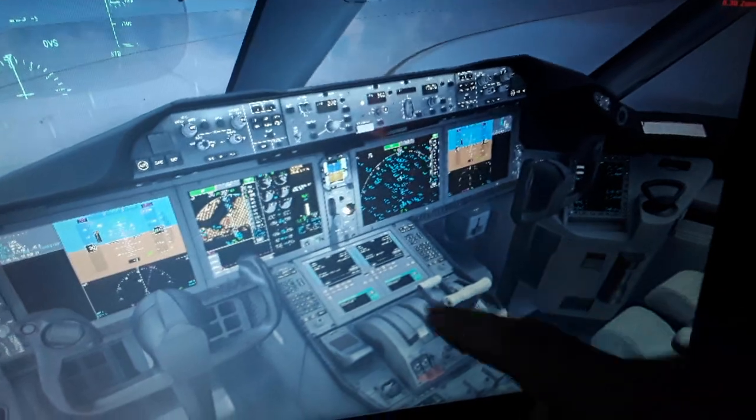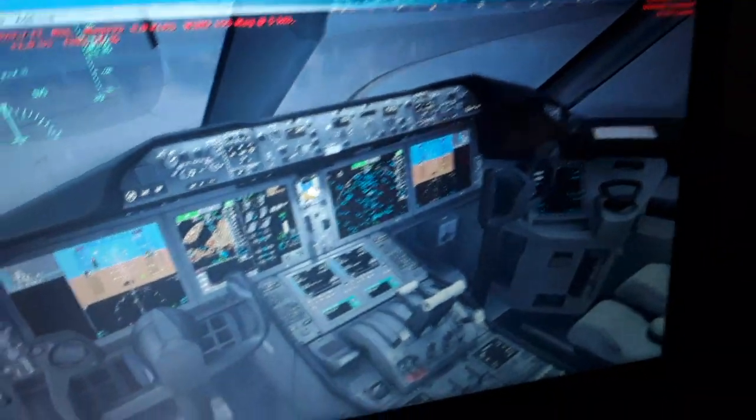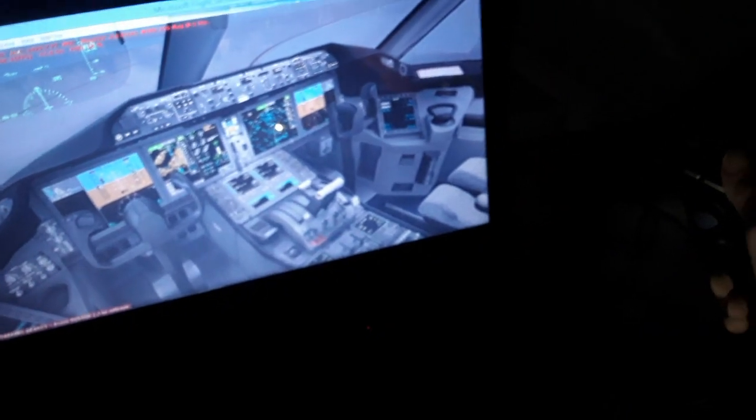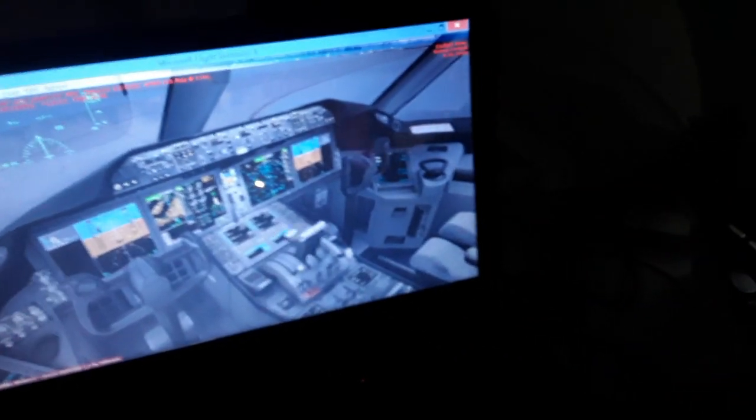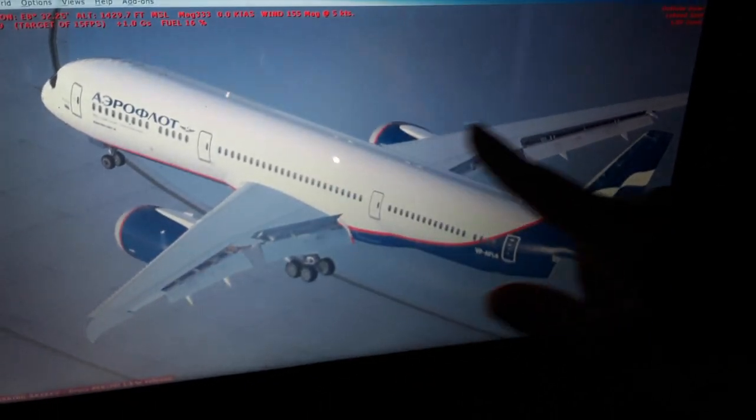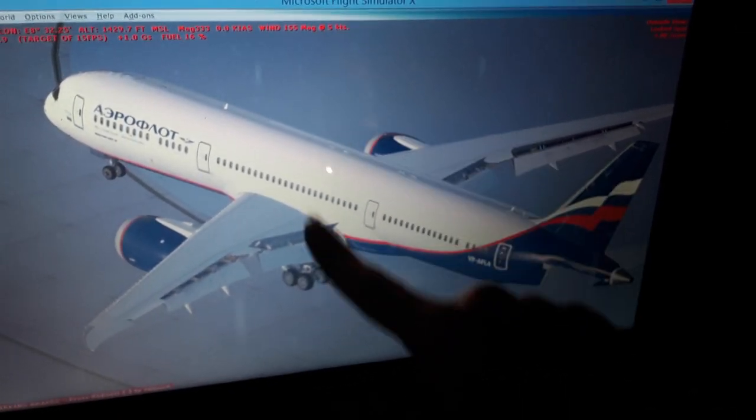Also the thrust here. We apply a nose down yoke or side stick if we have the Airbus, yoke if we have the Boeing, and the thrust levers forward to increase the thrust to make a stall avoidance. So we'll see mean aerodynamic chord position where the maximum aerodynamic lift occurs. Also is the center of gravity over here.